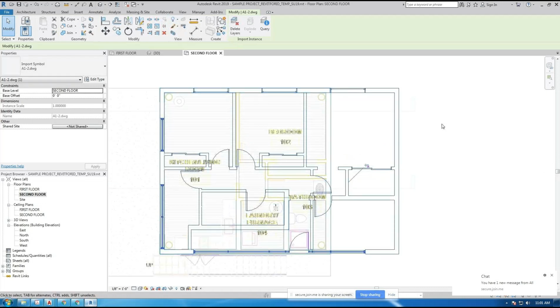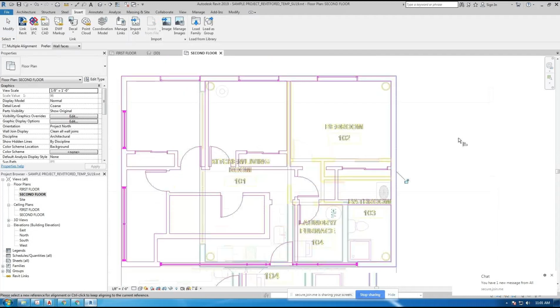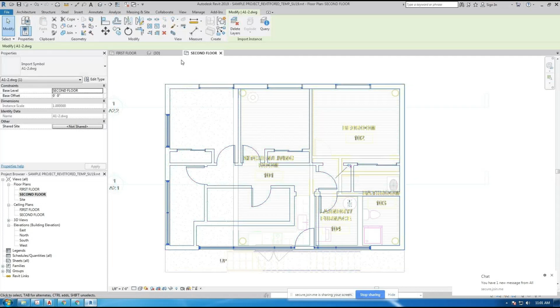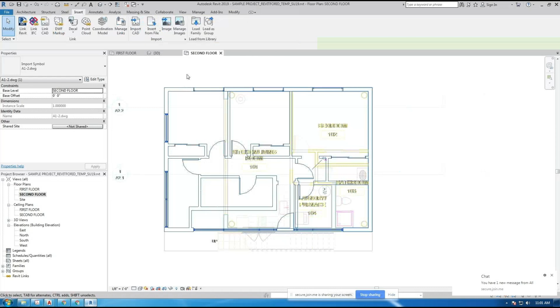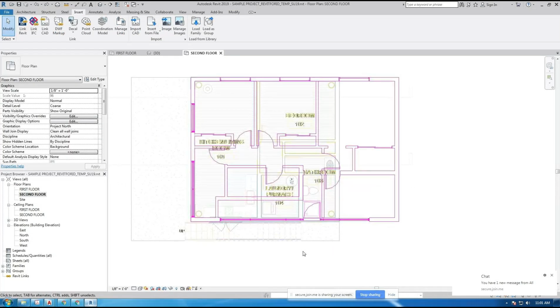Unpin. Then AL is Align. Go to here with this edge. And you see the drawing just slid over and lined up on that edge, because that's the alignment I wanted. Then what I suggest you do, you click on your CAD drawing, hit Escape, click on your CAD drawing, and pin it again right here, PN, pin it so it's stuck there, so you don't accidentally move it while you're working. And I'm going to undo that, Control-Z, and it's back to normal on the other side.